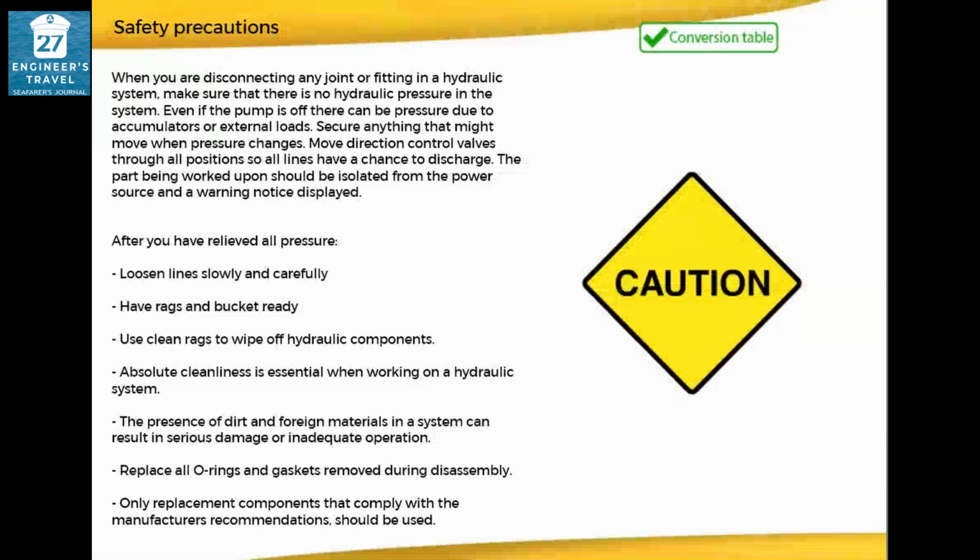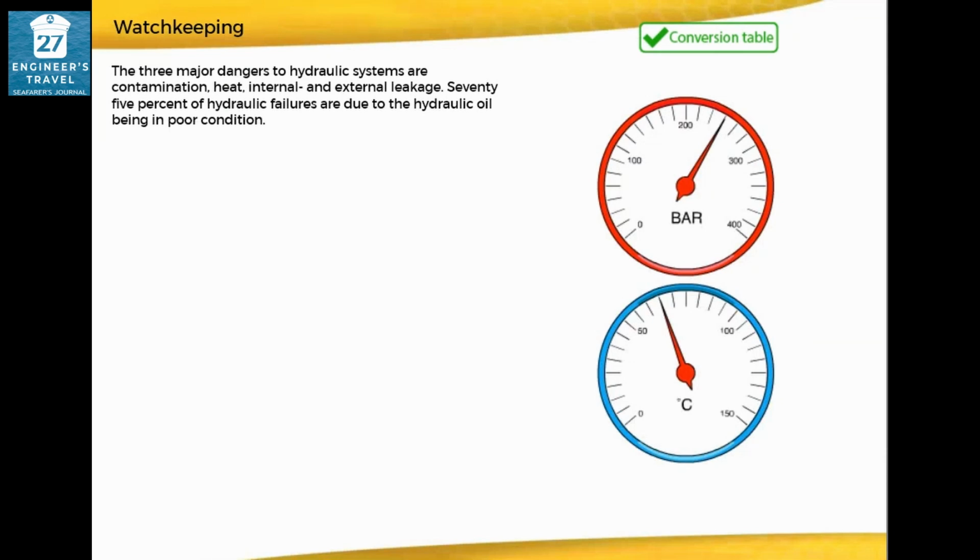Replace all O-rings and gaskets removed during disassembly. Only replacement components that comply with the manufacturer's recommendations should be used. The 3 major dangers to hydraulic systems are contamination, heat, and internal and external leakage. 75% of hydraulic failures are due to the hydraulic oil being in poor condition.